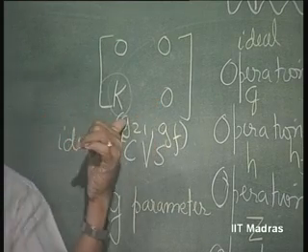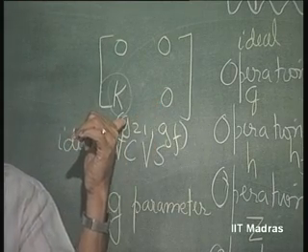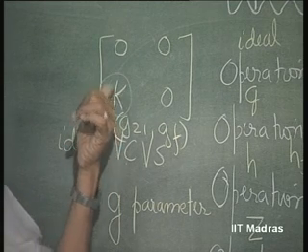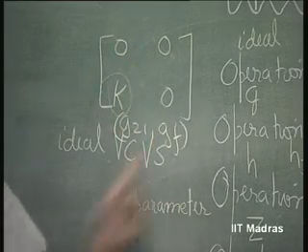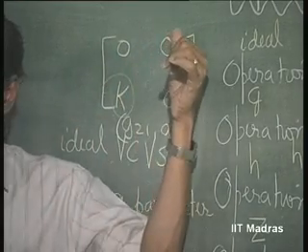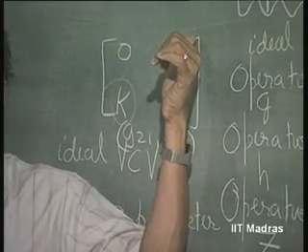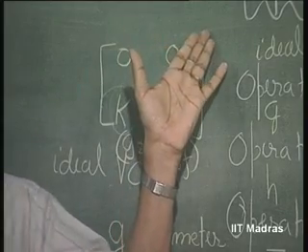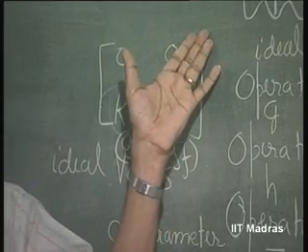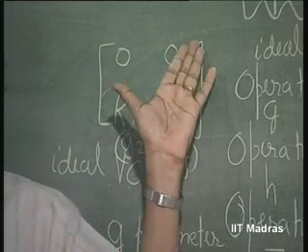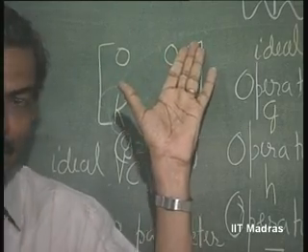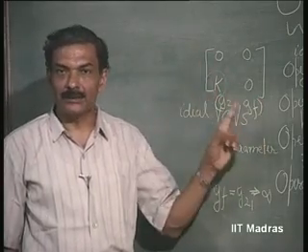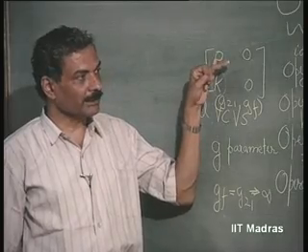When you cascade any amplifier configuration, we have proven earlier that if the forward transfer parameter of the individual amplifier is high, the reverse transfer parameter is going to be low. When you cascade, this becomes higher and this becomes lower. This is the basic effect of cascading. As you cascade, this will keep on increasing and this will keep on going towards 0. So, that is why cascading is a must in order to realize an operational amplifier. These two you have to design such that these two parameters are going towards 0. In this case, input resistance is made very high.